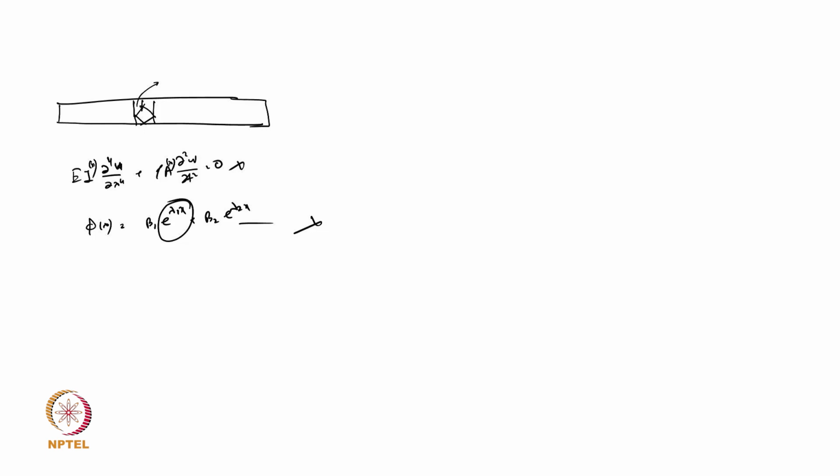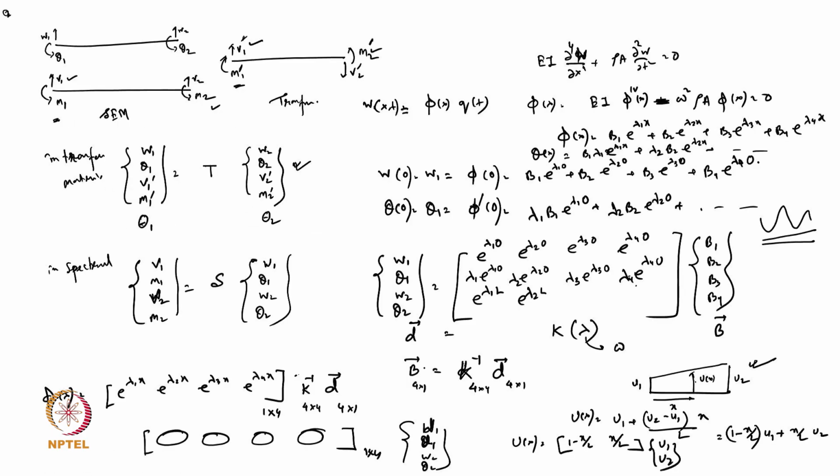If you do it with the finite element, you will end up with a matrix which you are directly able to solve. Let me just give you a quick example. Once we make that full stiffness matrix, it will come from omega, and that will be some transcendental function of omega, because our transfer function, if we just shift row and column, will give the spectral element matrix.